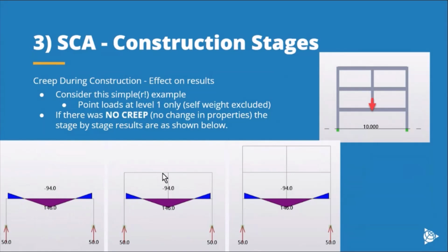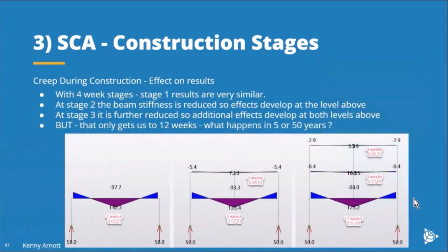If I then built a structure above it in a kind of weightless environment and just left it there, nothing would change. If there's no creep, nothing changes. You've got this locked in level of forces, stresses, and so on. So without creep, that's what you get. Run the same analysis again with creep. I've set it at 4 weeks.